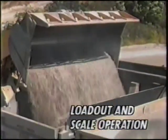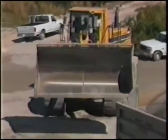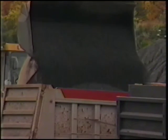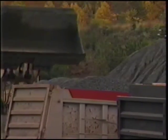Proper handling during loading is just as important as during stockpiling. Poor loading techniques can result in a segregated or damaged material. Various finished products, including riprap, coarse and fine aggregates, sand, and pug-milled materials are loaded into trucks or tractor trailers. This is done with front-end loaders or directly from storage bins.